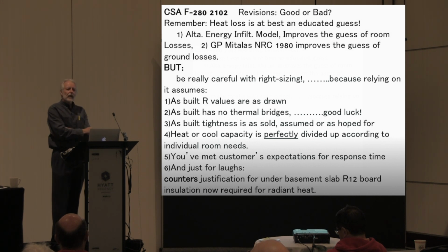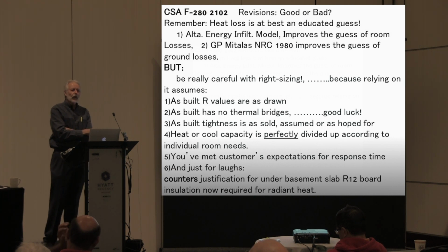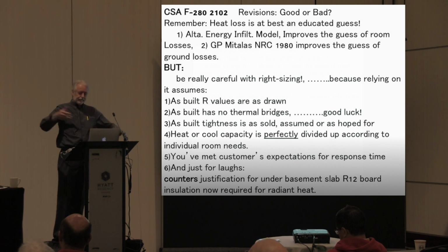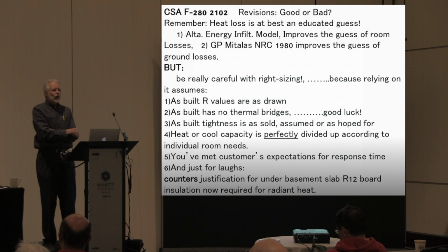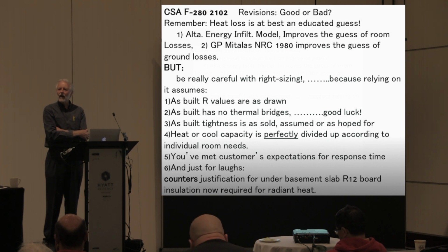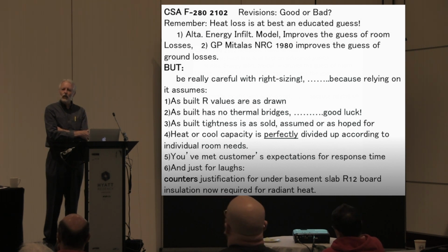Have you met your customers' expectations of response time? Mrs. Smith today, for right or wrong, is going to demand pickup. Now, the precise answer Scott and I will give you if you ask how much heat in your home is needed, is an answer you probably haven't heard. And that is, on January the 21st, the coldest day of the year, guaranteed, I checked the almanac, it is going to be minus 10 C, and your furnace theoretically should run nonstop 24 hours a day and squeak you to 22 degrees inside while it's offsetting that outside. And that's what F280 is going to give you. Is Mrs. Smith going to be happy if she goes to Whistler for the weekend and comes back and realizes the house doesn't pick up? Because you got 0 left over.